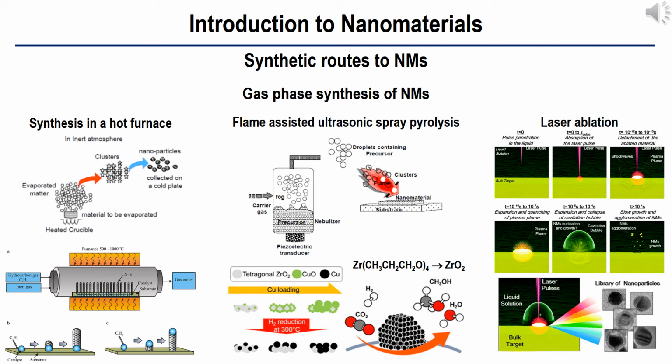However, since the gas pressure during the reaction is high, highly agglomerated powders are produced, which is disadvantageous for subsequent processing. The basic idea of low-pressure combustion flame synthesis is to extend the pressure range to the pressures used in gas phase synthesis and thus to reduce or avoid the agglomeration.